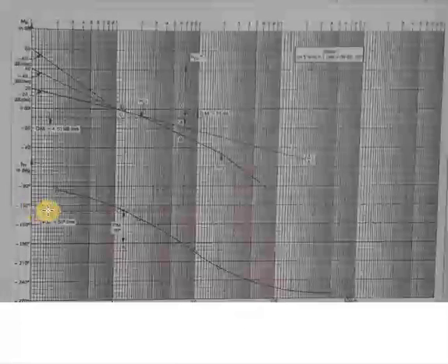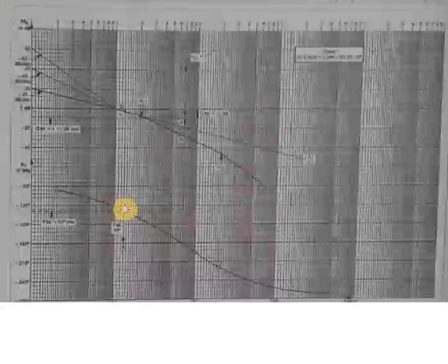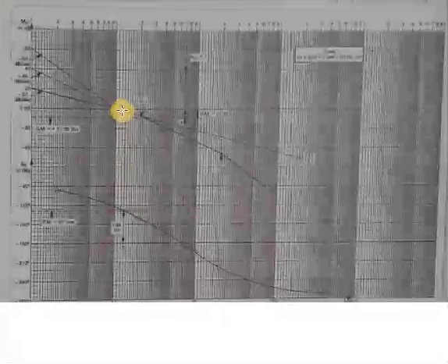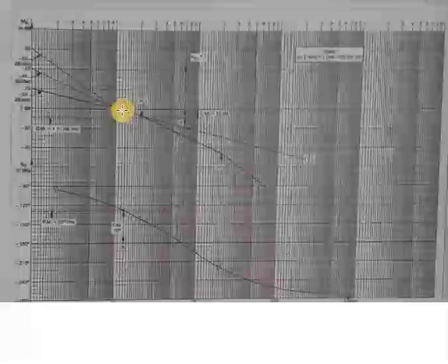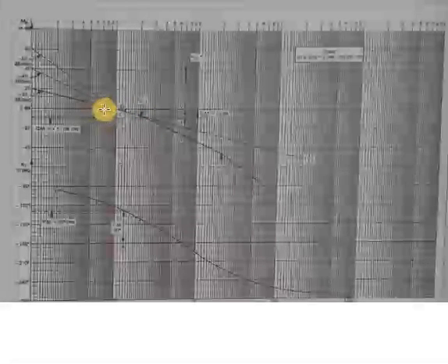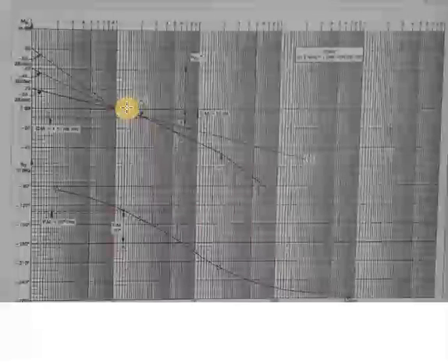So it is plus 50, and look for the intersection of this reference line with the phase plot. From there you draw a line up to the 0 dB line, and you will get the difference between the magnitude plot and the 0 dB line. That distance will give you the K value to have the phase margin as 50 degree.